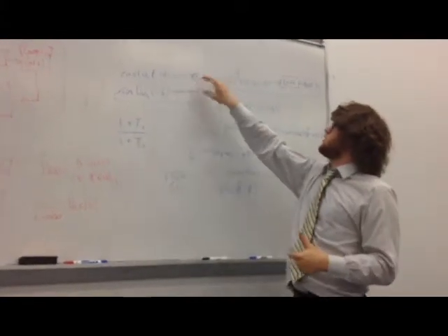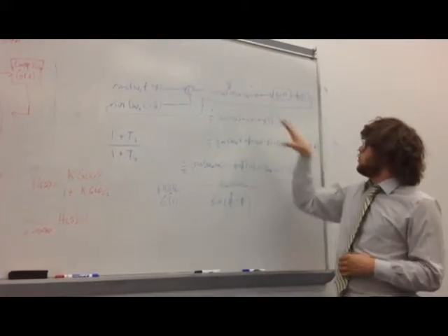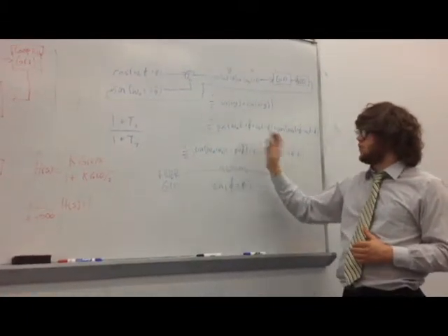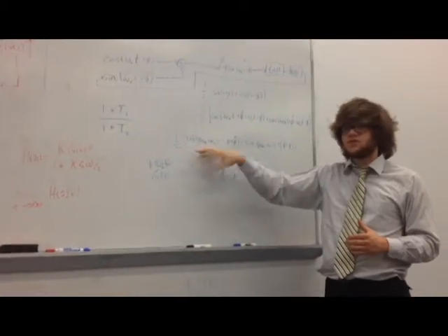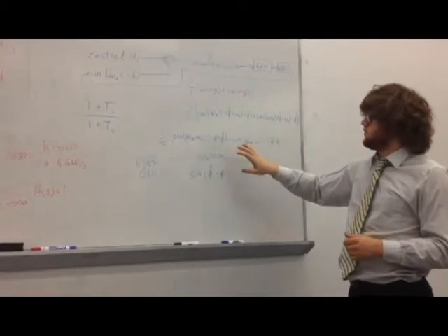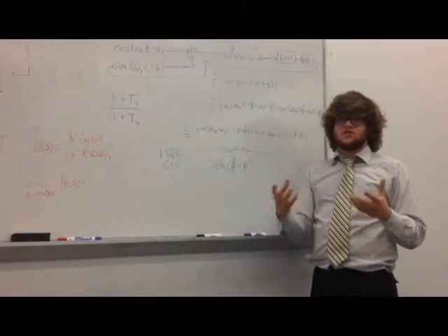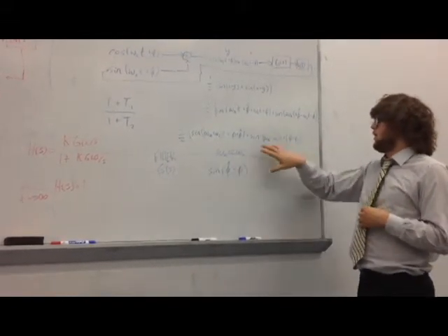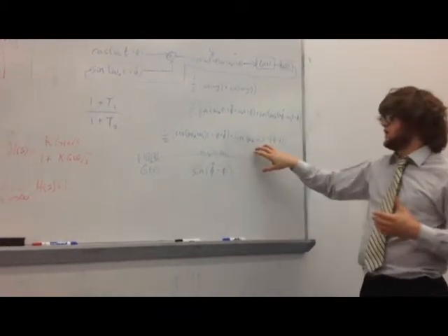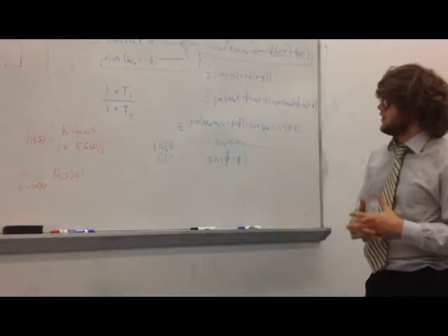We multiply those signals together and get the product, which after some math we see is one component at the sum of the frequencies and another component at the difference of those frequencies. Since those frequencies are roughly the same, the sum component is at 2 omega, and the difference component is roughly a DC offset, the sine of the phase error between the two.